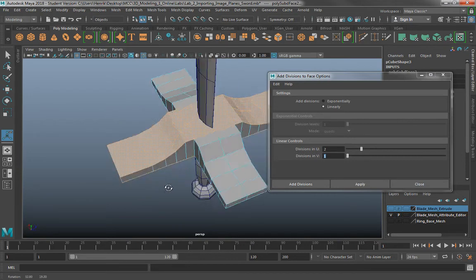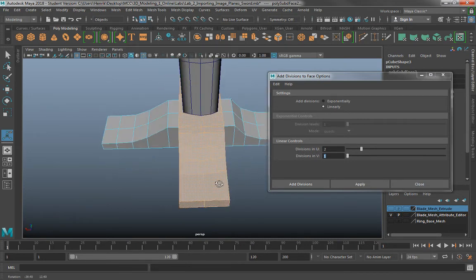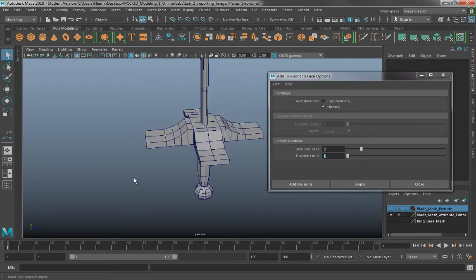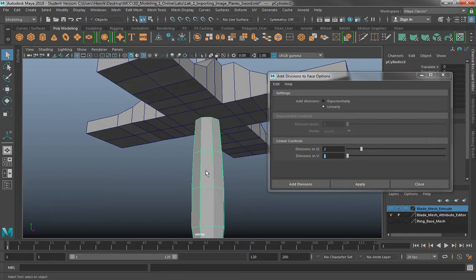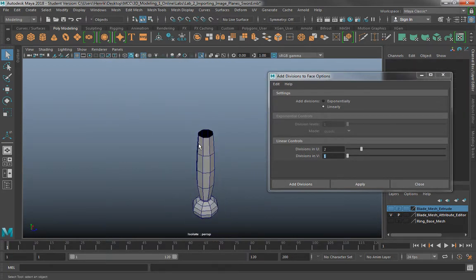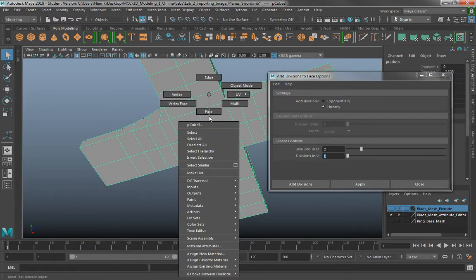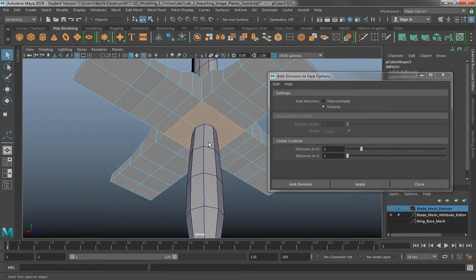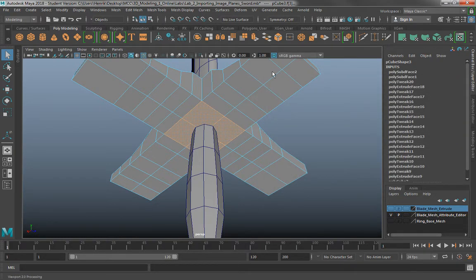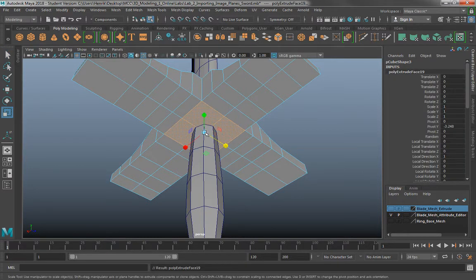And now we have some of our geometry that we're going to need in order to start to subdivide our shape here. Now, if I isolate this handle, you'll notice that this is still open because we deleted it before. And now, from here, I think it just works a little bit better visually if I select these faces. And I'm going to show you what I'm going to do here in just a second. I'm going to go ahead and use my Extrude Tool, as we just learned in the previous lab. And then I'm going to press R again, and I'm going to just middle mouse button inward, and you're going to see that